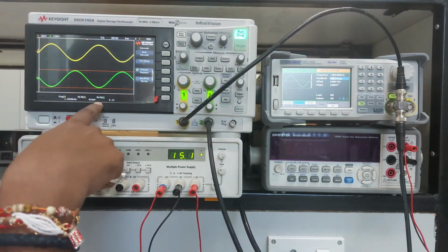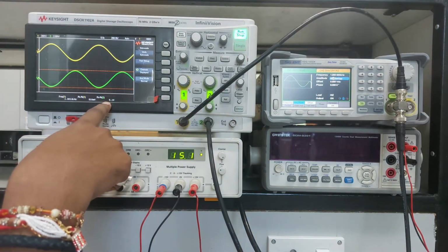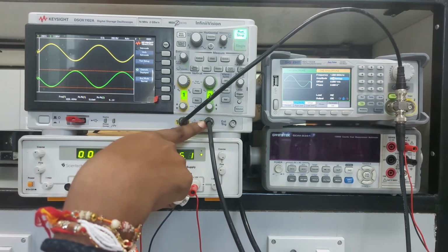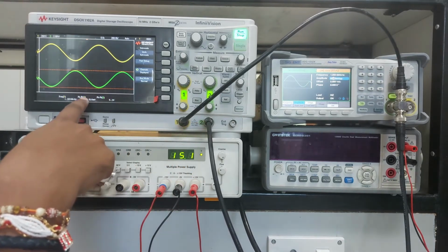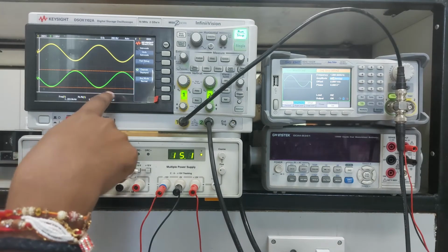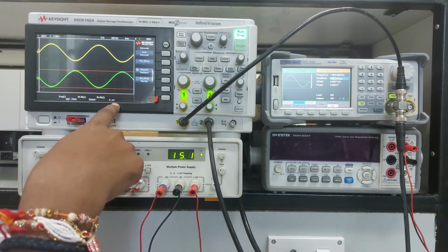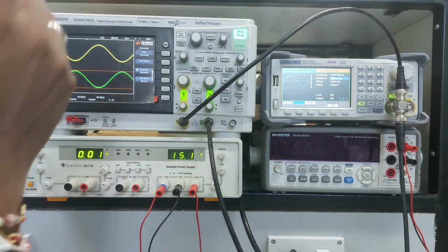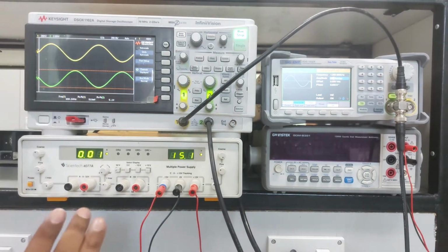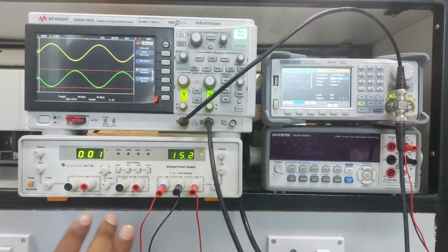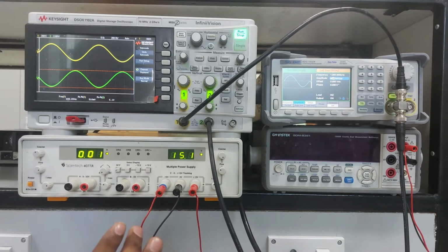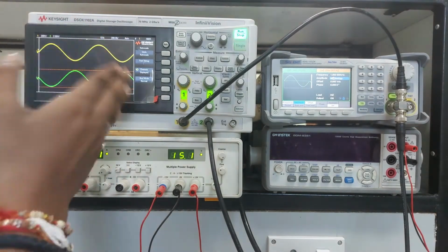But here you can see at the output, the peak to peak output, here it is written 2 because we are taking output from the op-amp at channel 2 of the DSO, which is 5.1. Input is 510 millivolt, output is 5.1 volt. Obviously this is 10 times larger, and we have fixed the feedback resistance, that is R2 by R1, which was 10 kilo ohm by 1 kilo ohm, that was 10. So feedback was fixed in such a way that the gain of the amplifier should be 10, and we are getting exactly the same.